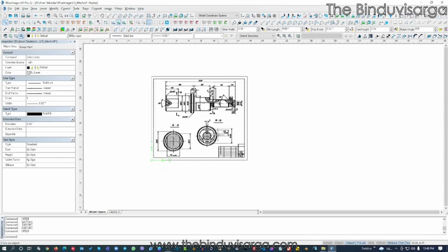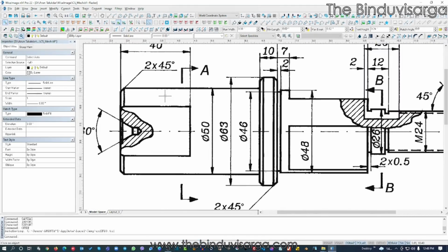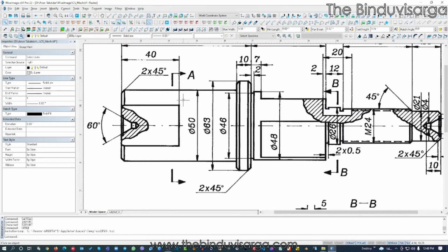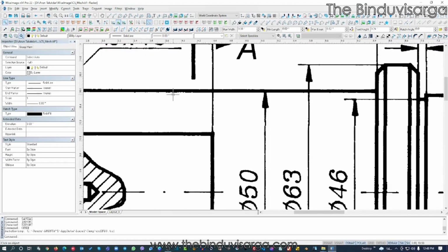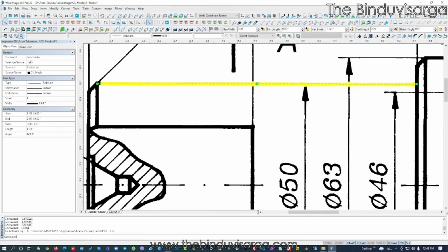So now let's see how we can use the modifying functions in WiseImage, right? This is one typical example we have inside the WiseImage demo folder. We can use that image to show you how we can edit raster images. Basically, when we open any raster image, that is editable, right? This is a specific raster image, so I can change line types, any parameters of that specific line.